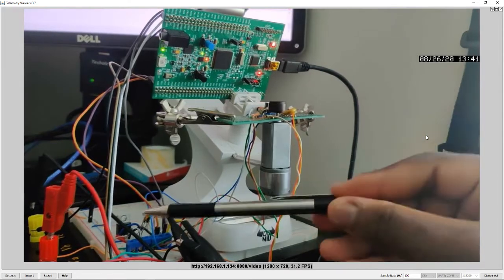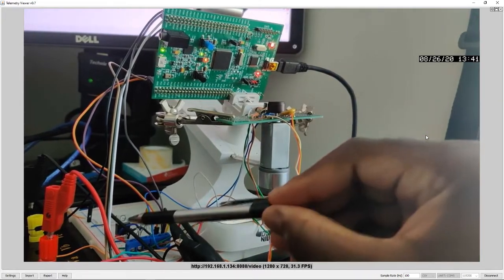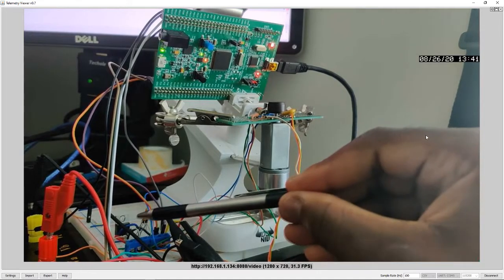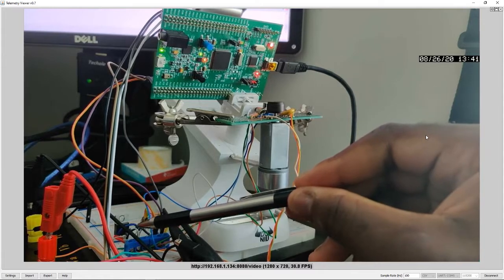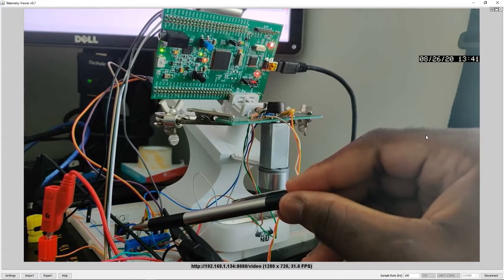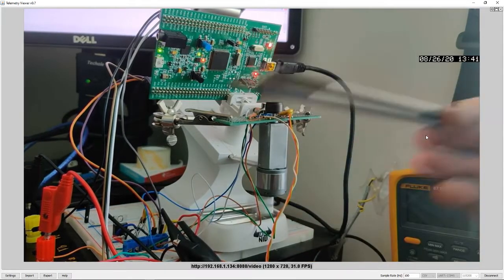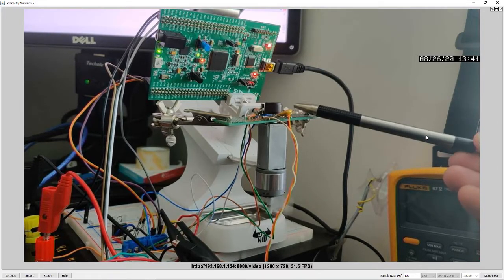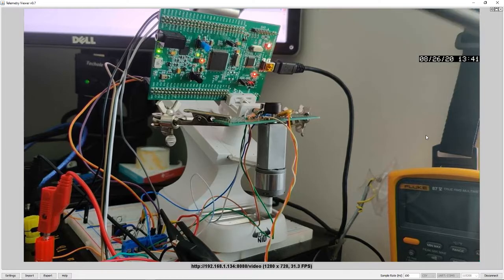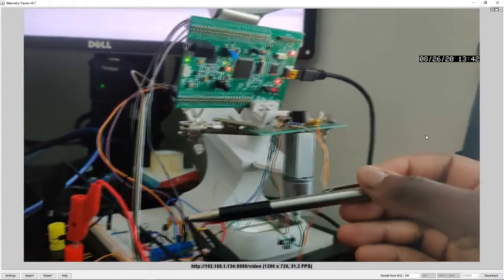I have the MOSFET that's driving the motor. Well, it can only spin in one direction since I only have a MOSFET. I have it configured as a low side driver with the load on the source. So the DC motor there has the suppressing diode there.